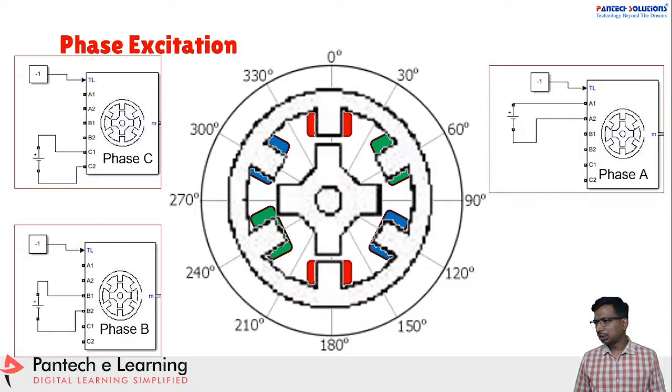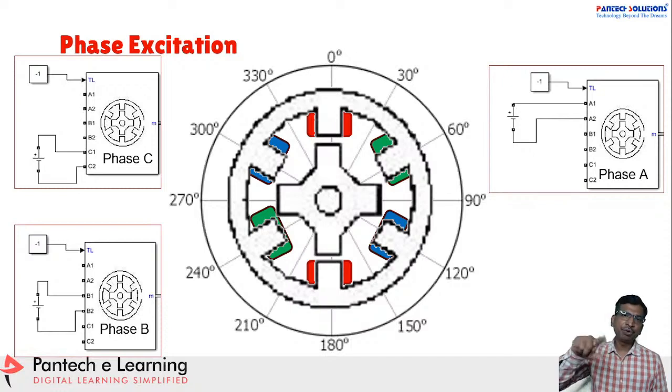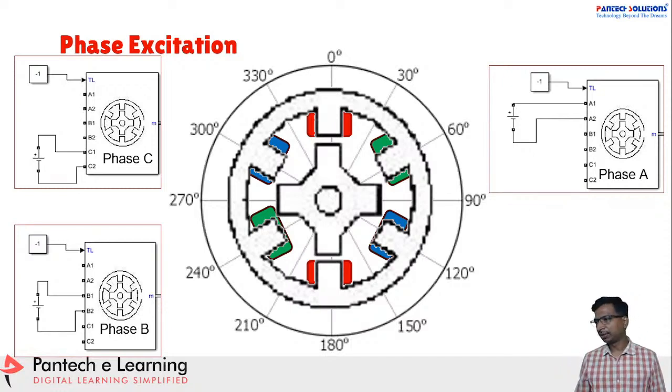When two switches are off, how does the current flow through the diode? See, actually, the diode will help us to avoid the peak overshoots on the particular coil. Any disadvantages like power loss? Yes, there are a few disadvantages in the SRM. I will tell you, so try to engage the entire session.